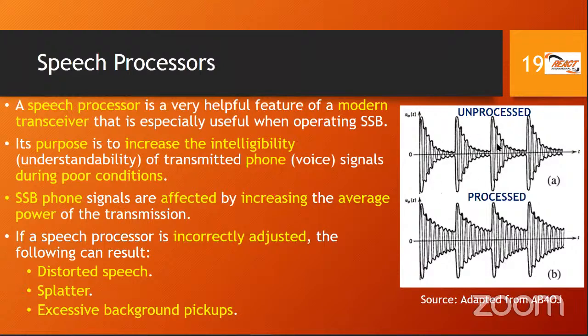So imagine that as a trained amateur radio operator, those of us who are probably already licensed and never use the speech processor say, oh, right, that's what my speech processor can do for me. I am going to use it now. So hopefully that has helped someone already. And as budding amateur radio operators, when you're purchasing your next rig, find out, do you have a speech processor inside of there that you can do this compression that we're looking at here? Because it can help you be heard when the conditions are poor.